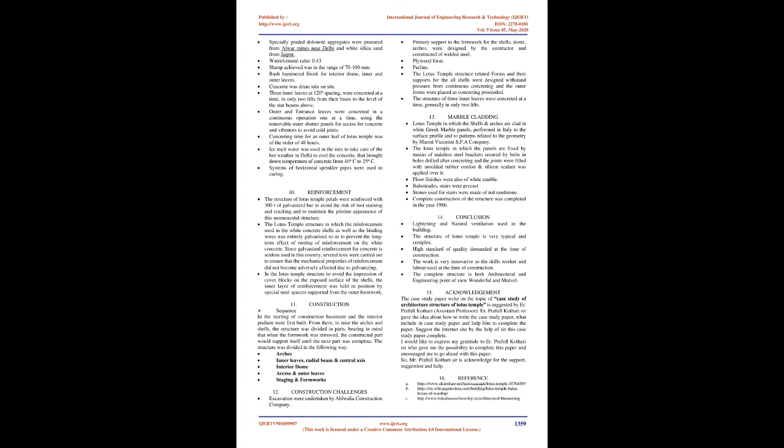Since galvanized reinforcement for concrete is seldom used in this country, several tests were carried out to ensure that the mechanical properties of the reinforcement did not become adversely affected due to galvanizing. In the Lotus Temple structure, to avoid the impression of cover blocks on the exposed surface of the shells, the inner layer of reinforcement was held in position by special steel spacers supported from the outer formwork.